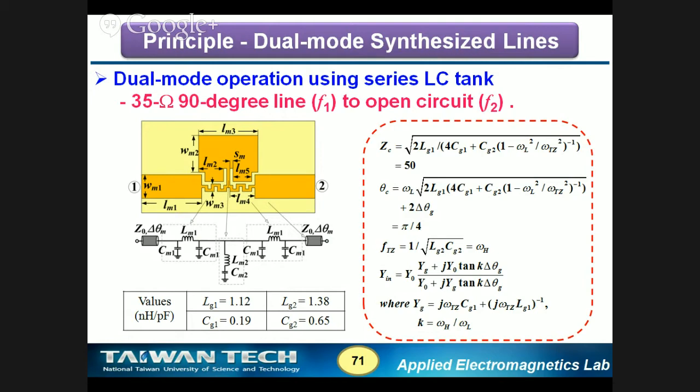And in general, from my experience, you should select inductance first. Because inductance is in general the most lossy component in this design. And also, it is the most distributed component. Lossy and has some distributed effect. For example, it has a self-resonance frequency or something like that. So if you have some degrees of freedom, you can choose the inductance first.